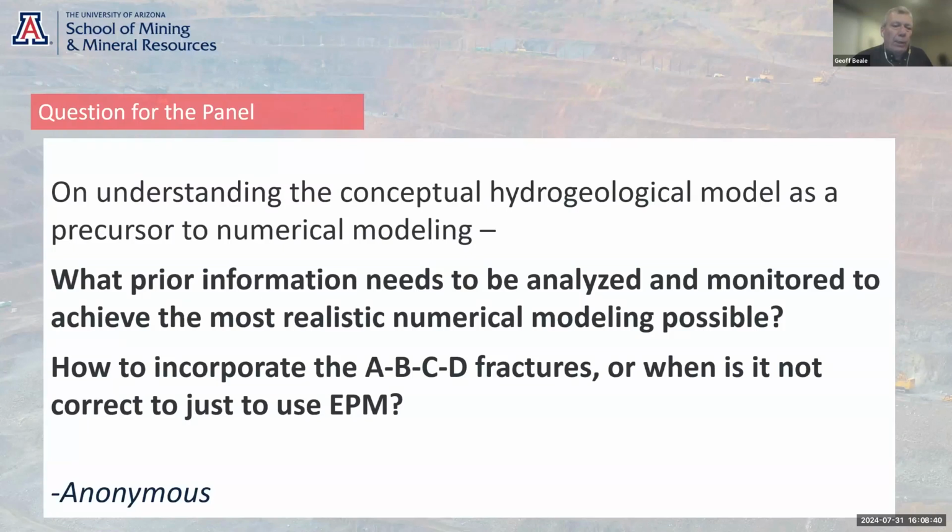You can calibrate a transient model to the changes in stress. It's very difficult to validate a model unless you've got variable head data, unless you've got responses of piezometers to some kind of pumping or excavation of the pit. So that's the most important piece of information, is responses of piezometers to stress.